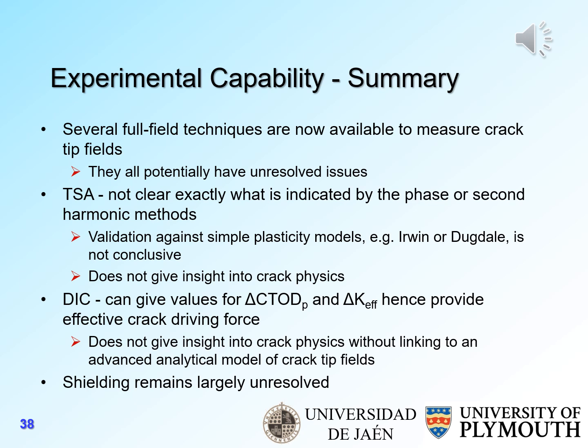DIC can give values for the range of crack tip opening displacement, the plastic range, and hence delta K effective may provide an effective driving force if you define delta K effective accurately, but it does not give insight into crack physics without linking to an advanced analytical model of crack tip fields. So after 50 years, in my view, shielding remains largely unresolved as a very important fatigue phenomenon.